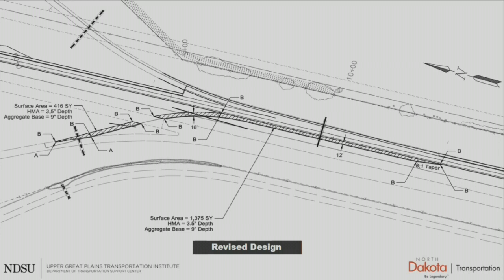And then finally, the determination of the type of surfacing that we're going to use for that type of ramp connection would be based on engineering judgment, but also a little bit of coordination with the personnel over at the district, since there may be reasons that they may or may not want to go with one surfacing or the other, aggregate or paving.